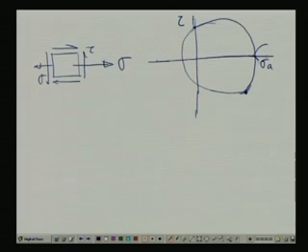This is a sigma axis, and this is the sigma A point, the principal stress, and this is another principal stress point, sigma B. So, we have the calculation: sigma equals how much? 26 into 10 to the power 3 to transform into Newton, divided by the area pi by 4 into 32 square.